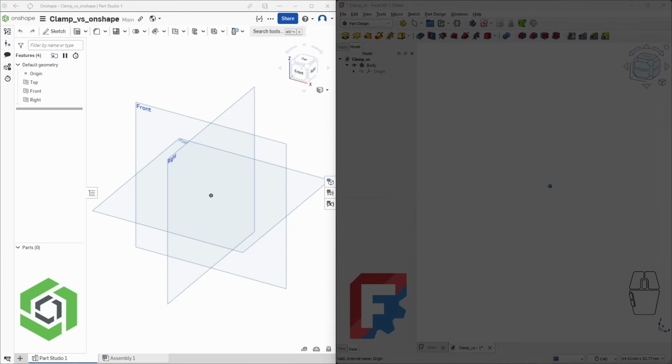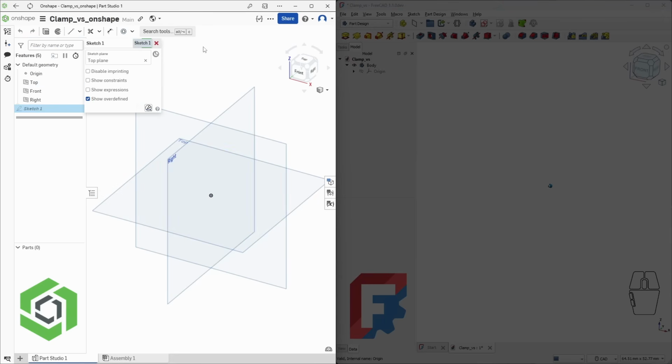Let's start with Onshape. The interface may differ from yours because I had to resize it to fit the screen. To create a sketch, you first need to select a plane. In our case, we choose the top plane. So, left-click on the top plane, then click on the sketch icon in the top menu. To make it easier to draw, we'll click on the word top on the navigation cube to align the view perpendicular to the sketch plane.